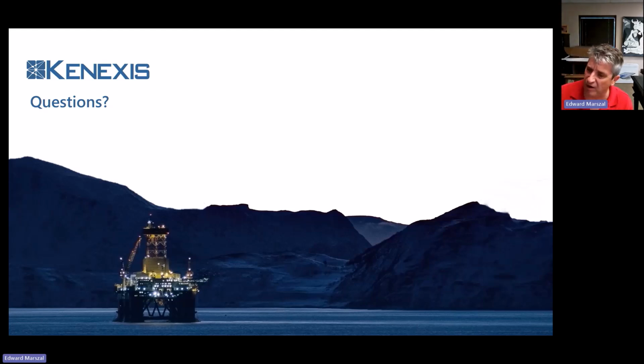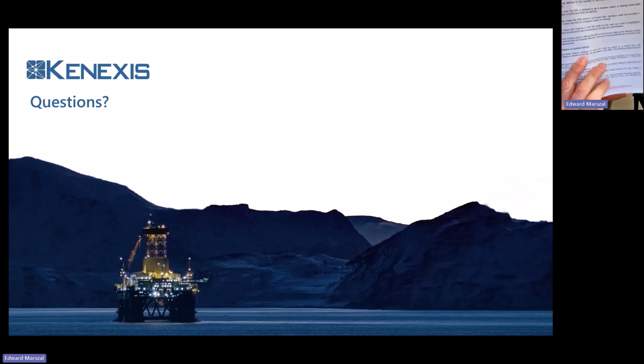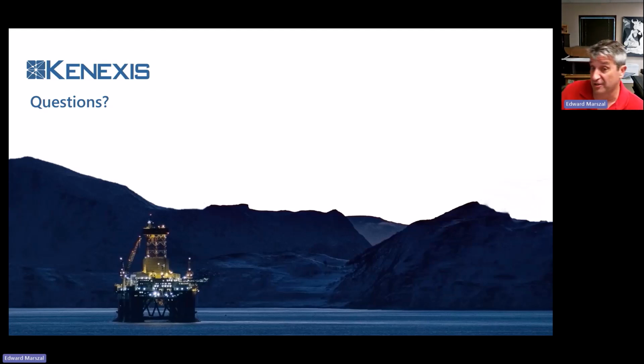Right in the title, when it's talking about PFD, the title says quantification of random failure. So right out of the gate, you should be asking yourself whether or not you should be modeling systematic failures. And the standard is pretty clear that the answer is no. And it will actually lead you to the wrong answer, and I'll get into that in just a second. But it says, 11.9.1, the calculated failure measure of each SIF shall be equal to or better than the target failure measure. And then it says the calculated failure measure shall consider, and it says estimated failure rate of dangerous